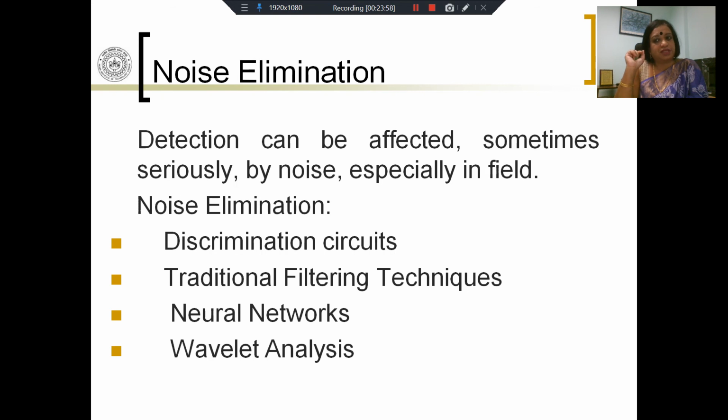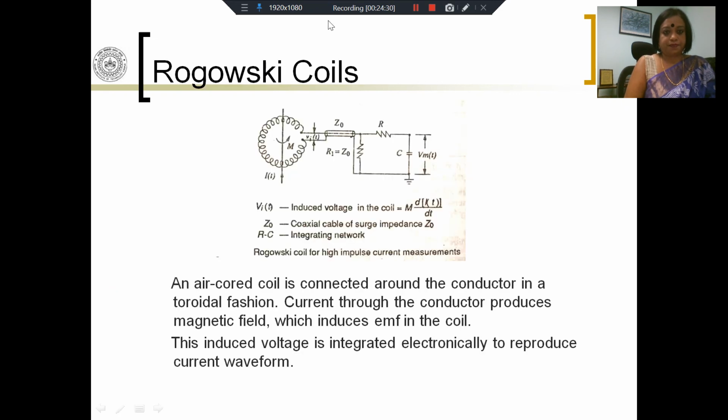This is not always possible, especially since often we do not have a priori information about what kind of noise to expect. And in that case, if you look up the literature on research of partial discharges, there is a large amount of work on signal processing of the data, where we use things like wavelet analysis or neural networks. A lot of work has been done towards eliciting useful information from the measured data.